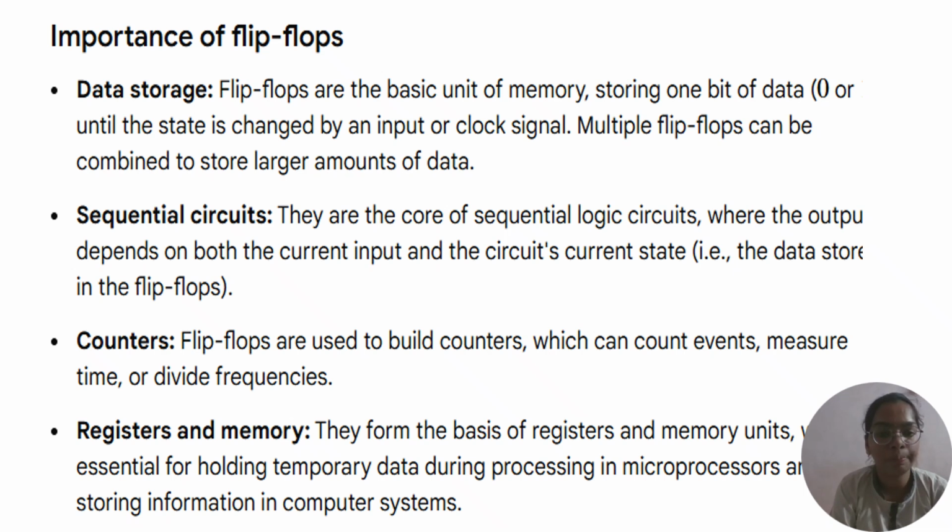Importance of flip-flop. First one, data storage. Flip-flops are the basic unit of memory, storing one bit of data, 0 or 1, until the state is changed by an input or clock signal. Multiple flip-flops can be combined to store large amount of data. The second one is sequential circuits. They are the core of the sequential logic circuits where the output depends on both the current input and the circuit's current state, that is the data stored in the flip-flop.